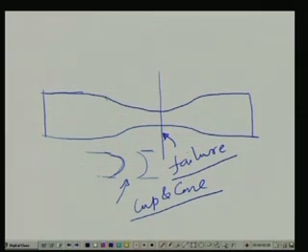Basically, before this failure takes place, this particular shape comes out by sliding of the planes at an angle of around 45 degrees, and then it gradually elongates. When it crosses the yield point, it goes to the plastic state, and then this fracture takes place.